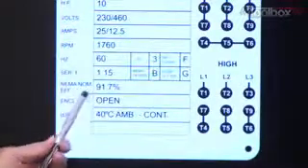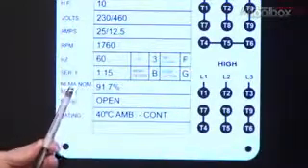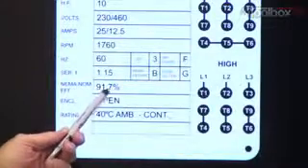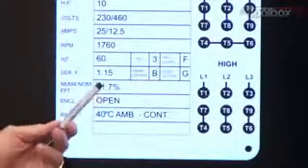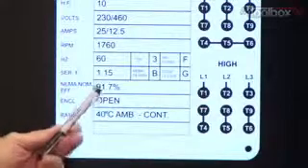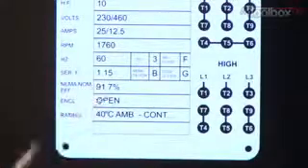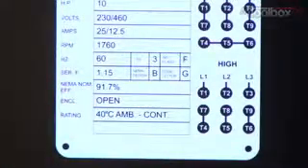Down here, you've got nominal efficiency, NEMA nominal efficiency, 91.7. That means that 91.7% of the energy that this motor is consuming is actually going to real work, the work we meant to do. The rest of it is being wasted by heat in the conductors, magnetic fields causing currents in the laminations, I squared R loss, lots of other kinds of things, just inefficiencies inside the motor.